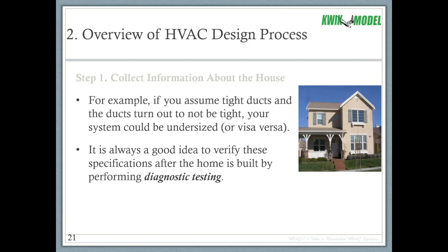It's always a good idea, if you can or can have somebody do it for you, to verify things in the house such as duct leakage, and the other big one is infiltration, doing a blower door test on the house. We call that diagnostic testing. That's going out to the actual house and measuring those things. If you can get that information, that is great. If you don't have that information, your margin of error becomes much higher, with more potential to be off.